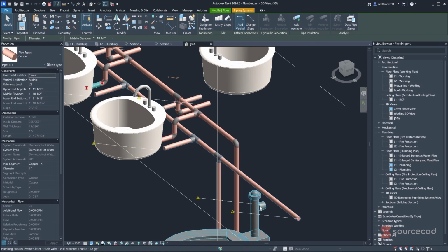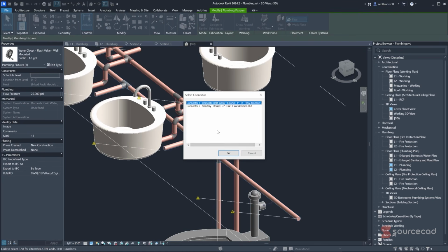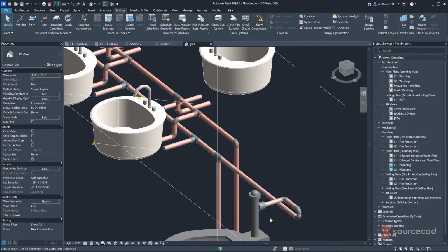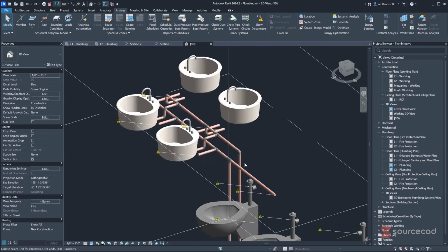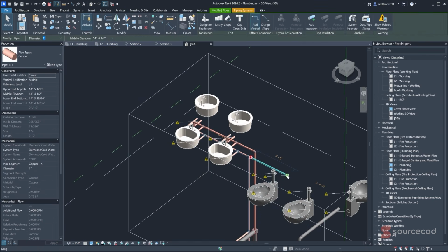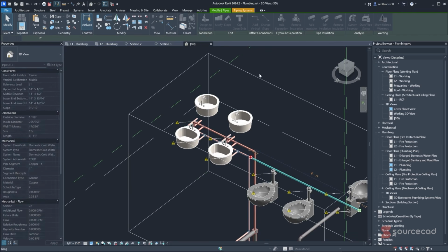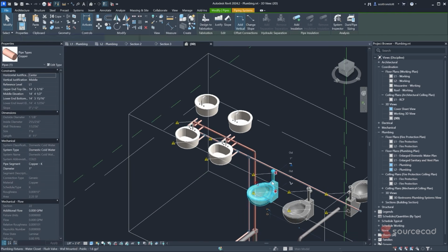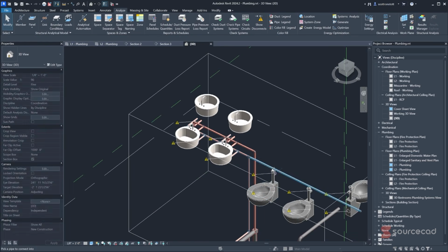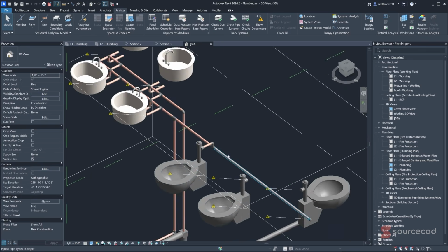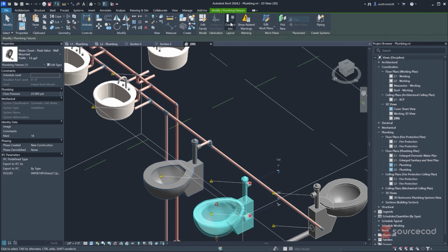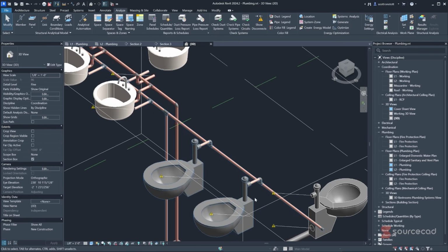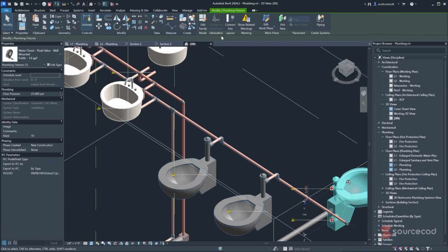This has to go into the pipe over here. So I'll say connect into cold water. And you see how it took the circuitous route? That's not what I wanted. Undo. What I'm going to have to do is pull this down far enough and then cap it. And then I can connect into the cold water line, and it will find the right routing solution because there's only that possibility. Here, connect into.